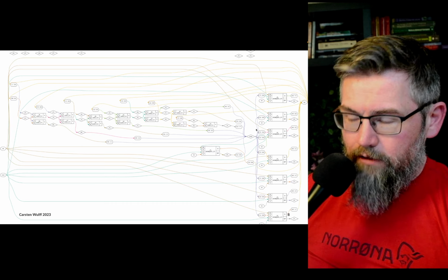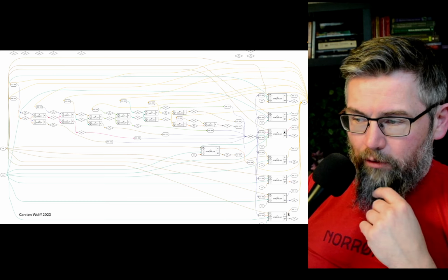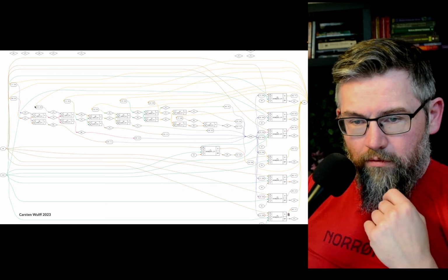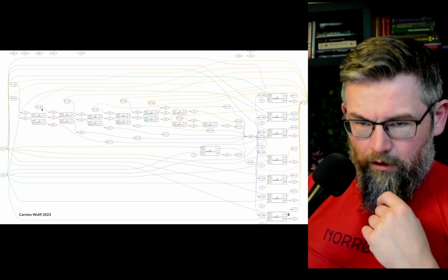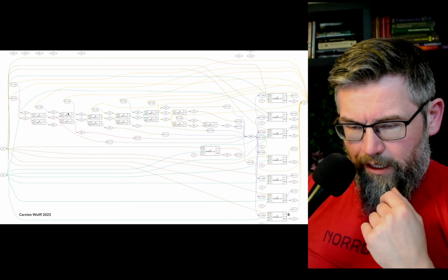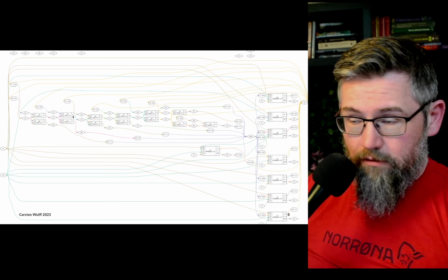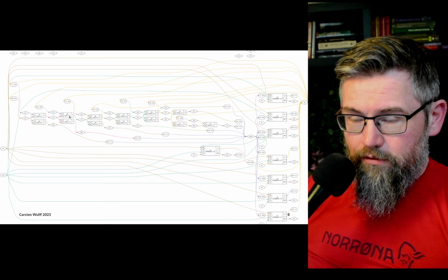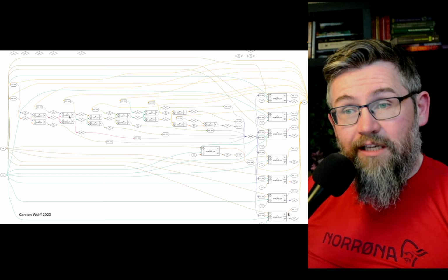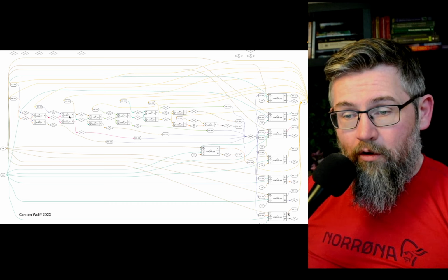So that means, for example, as soon as we set a bit out here, as soon as that bit changes, that will ripple back and events will be added into the queue. For example, here, I think this is bit 2. Well, then we have to add an event to the queue where the Y output of the AND changes. And then it ripples through. Now this is at the RTL level, so it might have some sense of what happens when. Maybe there's some delay in the AND in the Verilog, or maybe not.